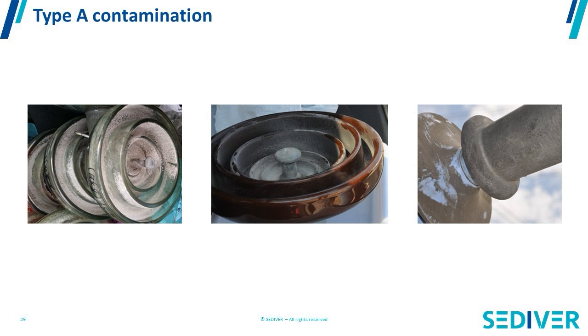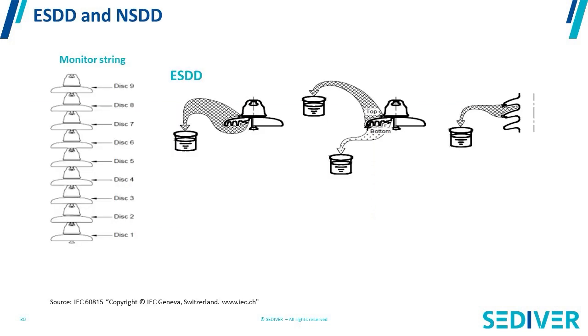Typically, and you probably have seen many insulators like that in China, dust, either dust from the desert or industrial dust, will actually sit on the insulators and work like a sponge when you have some moisture. So there are two words you need to know when we are talking about pollution. They're actually acronyms. The first is ESDD. ESDD is an acronym which means equivalent salt deposit density.